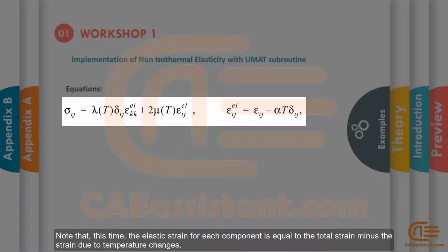Note that this time the elastic strain for each component is equal to the total strain minus the strain due to temperature changes. Therefore, we see temperature-dependent terms in stress and strain equations compared to previous basic stress-strain relations.